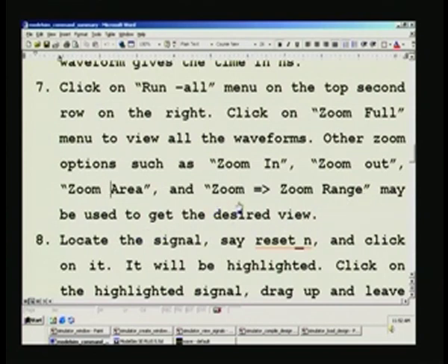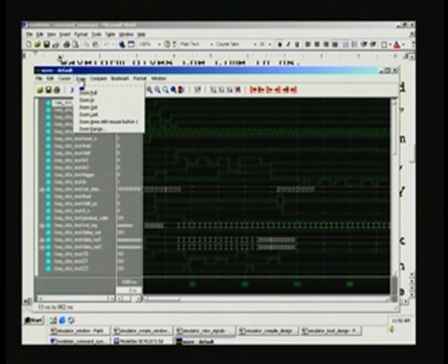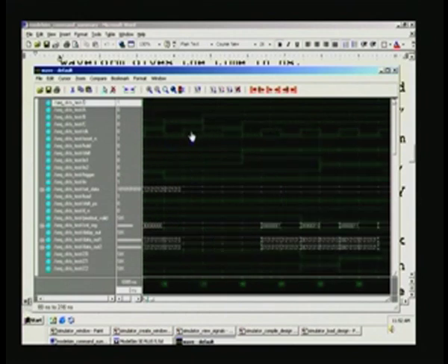So, in zoom let us see the waveform here once again. You have one zoom menu here. In zoom, we have just now seen area marking. There is also the area marking here, zoom area with mouse button 1, so you can use that. And another thing is range. Suppose you want, let us look at this here. You see the very same thing, cursor has changed, and I can mark as I had done earlier. So, it has zoomed in the area that you have marked.